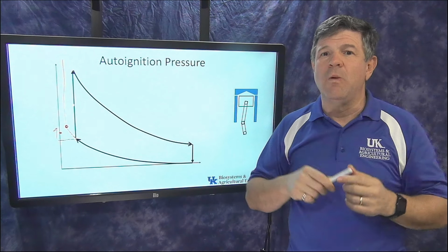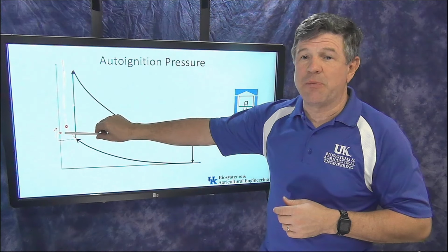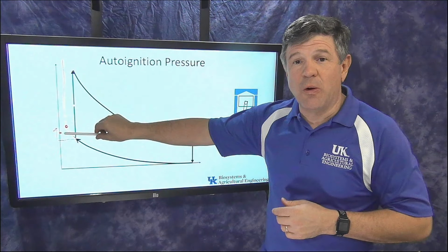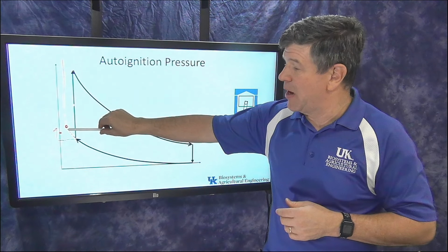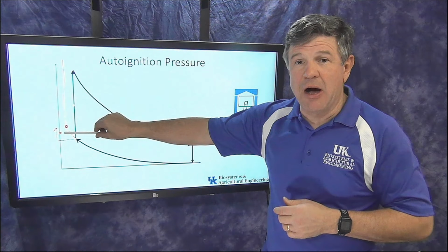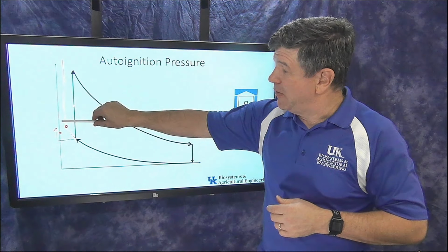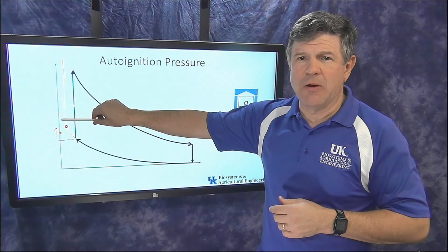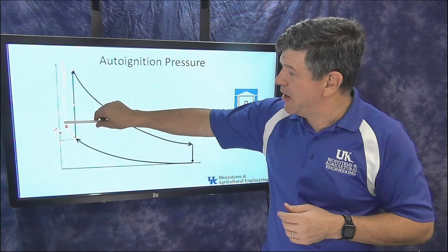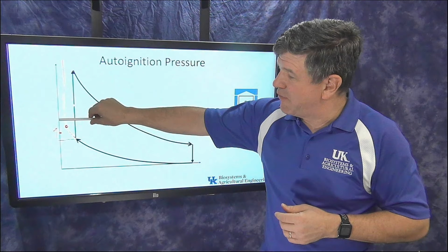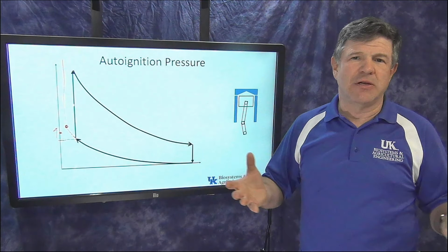So that's when we talked about auto ignition pressure, octane of fuel. Low octane fuel has a pressure down here. High octane fuels are going to have a higher auto ignition pressure. So if I have a situation like this where my pressure in the chamber is above my auto ignition pressure of the fuel, I've got to do something with the fuel to have a higher auto ignition pressure so it doesn't burn when I don't want it to. So there's 87, 89, 95 octane, whatever. The higher octanes, I'd have to get a different fuel with a higher auto ignition pressure to operate above that. So that's the other thing that we've got to be careful of as we change pressures.